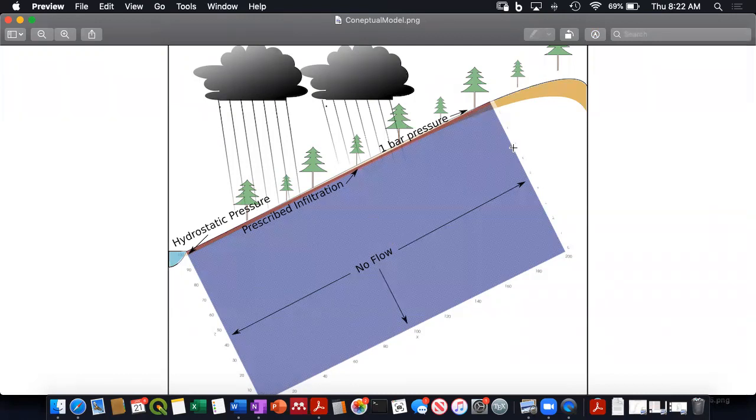It's a block that's tilted. So it's a hill slope. And the top 2 meters of it are soil, and then the bottom 98 meters of it are bedrock. All right. And there's a contrast in the properties between the soil and the bedrock. And then what I do is I apply snowmelt and precipitation taken from actually a SNOTEL in the mountains near Missoula, which is an instrument that measures precipitation and snowmelt in the snowpack.